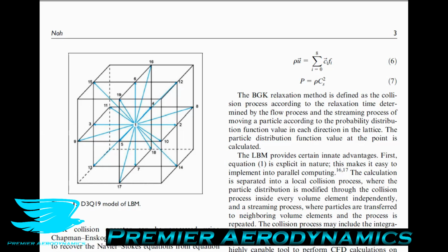And this is important because they say the Lattice Boltzmann method analyzes flows using the Boltzmann equation as the governing equation, which defines the behavior of particles, including movement and collision, in a discretized lattice as a probability distribution function. The Bhatnagar-Gross-Krook model, BGK in other words, with a single relaxation time with the D3Q19 model, which uses square grids in three-dimensional space, are widely employed because the collision term of the Boltzmann equation is considered.